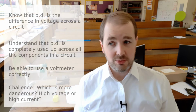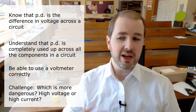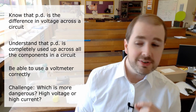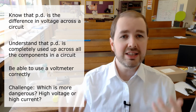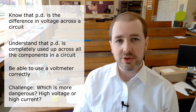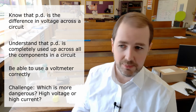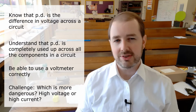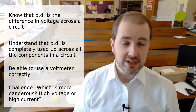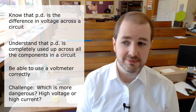By the end of this video, what you're going to know is that potential difference is the difference in voltage across a circuit and also individual components. You're going to understand that potential difference is completely used up across all the components in a circuit, as in it starts at a high bit and then ends up at effectively zero. And you should be able to use a voltmeter correctly, as in hook it up to a circuit in the correct way. It is different from the ammeter we've done before, so make sure you pay attention.